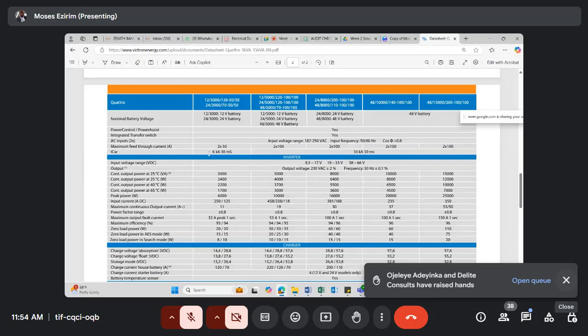You understand? If you notice that, okay, this is what the client load is. What if the load is not? What if the energy is not like that? You understand? So, like I mentioned, when you design, when you've done your audit, you know the client's load, and you know what the charging capacity of the battery is, and you size based on what I've just done, then you are good to go.